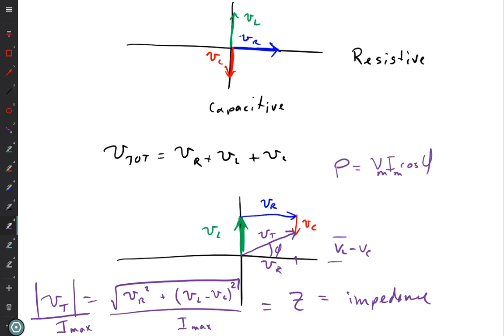And so if that phase angle is 0 degrees, then your actual power will be equal to your apparent power. And you'll pay for what you're using. If that phase angle was 90 degrees, that is if it's purely inductive, let's say, or purely capacitive, you're not using any power. But you would still get charged for power from the power company.